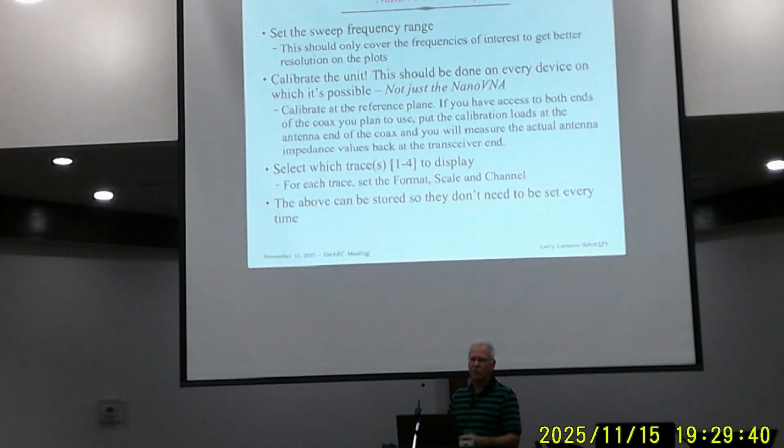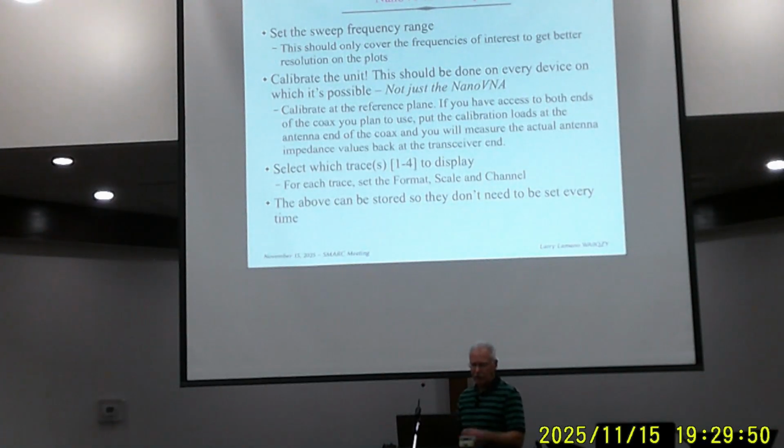So you have to hook it up to the balun rather than the coax. Well, you can hook it to the coax, but again, you want to calibrate that coax where it goes with the balun up there. And then that'll read what the balun sees, if that makes sense. So if it's a 4 to 1, you should read 50 ohms more or less, up there.